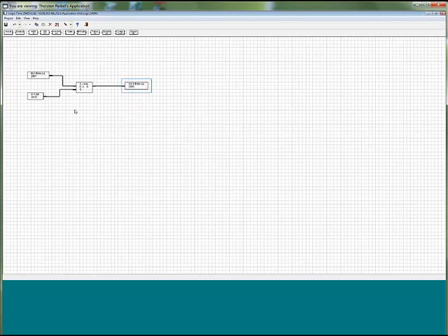This one, for example. And depending on this control input, if the value here is 0, this group address now is blocked. But now when I enable my input, so I'm absent, which is the value 1, this gate is open, and this group address now goes inside my gate and is forwarded to KNX with this group address of the same value. Good, so far the principle: insert inputs, outputs, and link the elements here with our input element and the output element, and save.